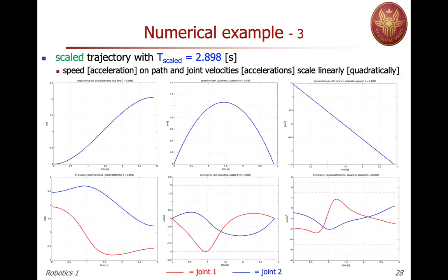So we have scaled by the factor k that we have chosen, the Cartesian speed. And of course, same story by a factor k squared, so by a factor about 9, we scaled the acceleration. In fact, you can see that it's around 1.4. We had 12 or 13 to start with. So this is the scaling on the Cartesian trajectory, and of course also on the joint motion. The first plot in the second row is the actual joint motion, which has not changed at all.